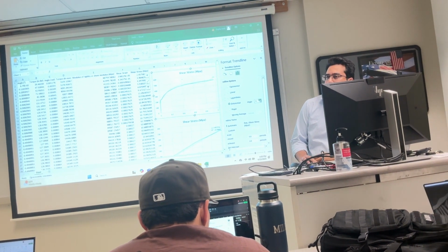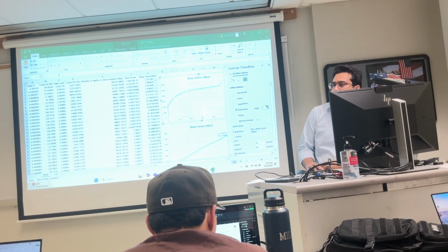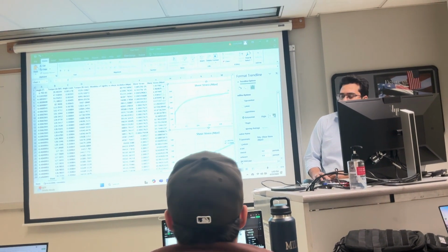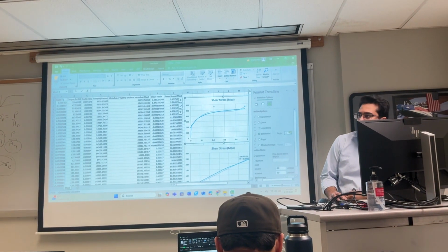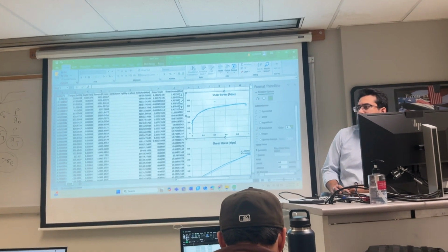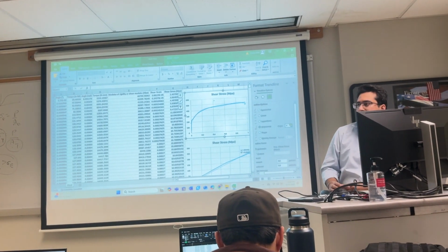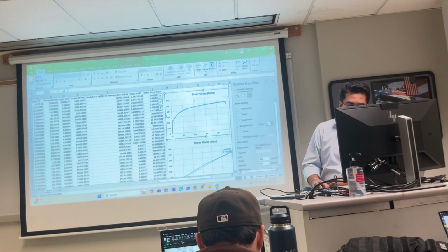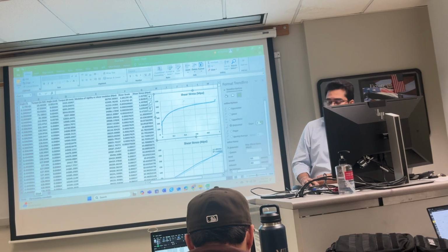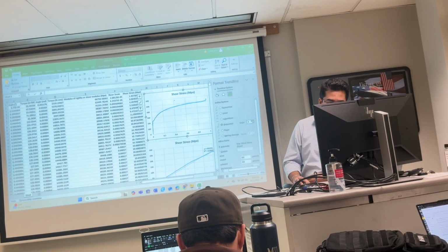You guys are following, right? Good, right? You know why I deleted that initial data? To cut off that end line that dips down, because it will mess up the proper curve. And that's on the original stress strain curve? Yes, always. Right, so we just throw those away?